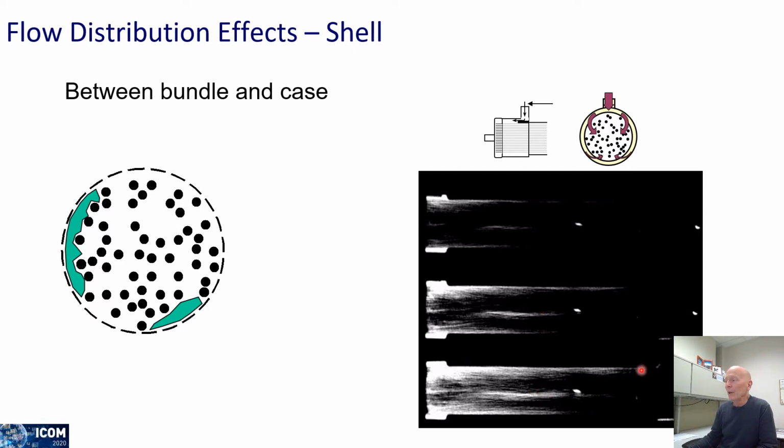And in fact, you see the fluid at the top of the case here, at the gap between the fiber bundle and the top of the case, actually exits the lumen manifold well before we fill in most of the module. So what is the impact of having this type of performance, this type of velocity distribution within the fiber bundle? What is the impact of that on performance? It's not well understood for liquid separations, and it's less well understood for gas.